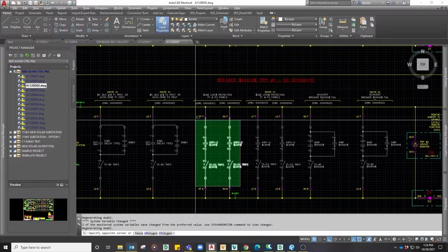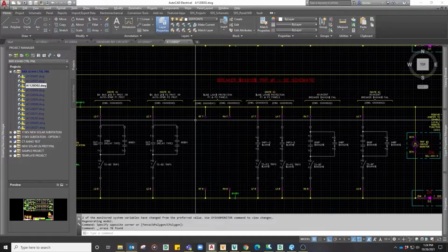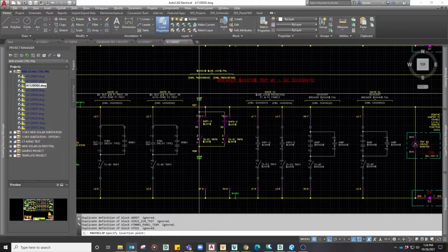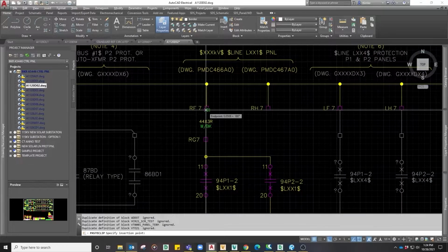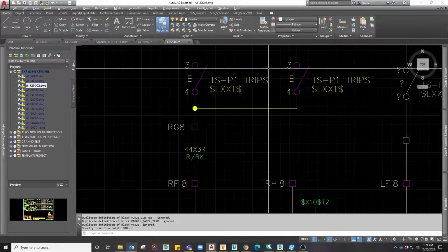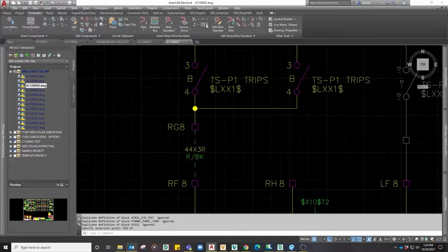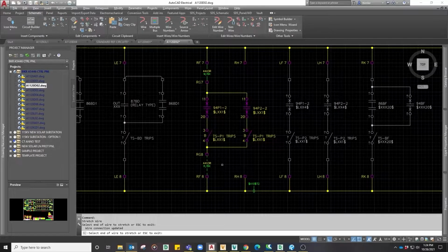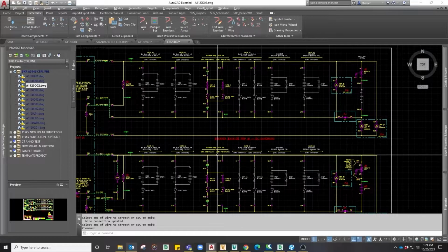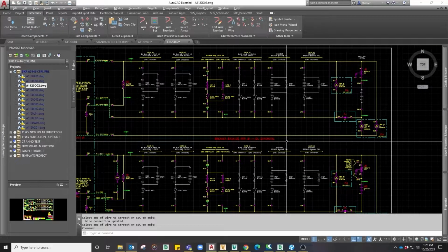So I'll grab the second circuit, and I'll go to the bottom trip circuit on the breaker control panel, delete the circuitry, delete the description and drawing cross-reference information, and snap this circuit to the midpoint as well. At the bottom here, the wire is not touching, so I'll select stretch wire and just stretch that wire to the connection point attribute of that schematic terminal.